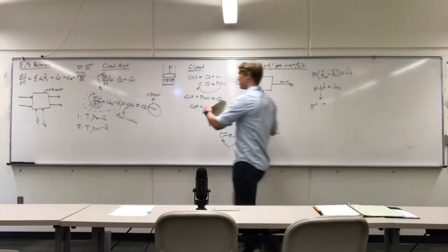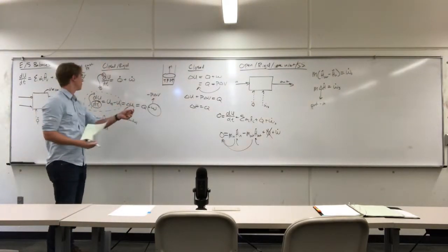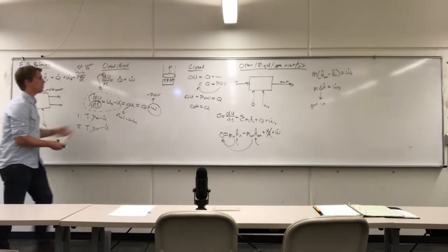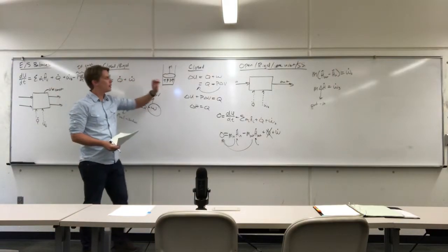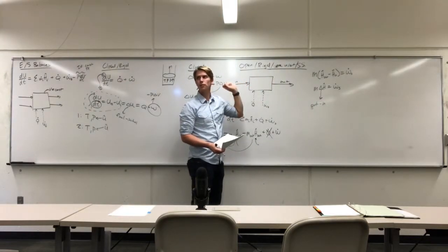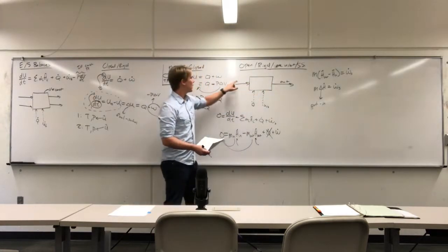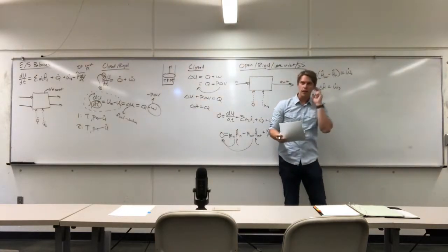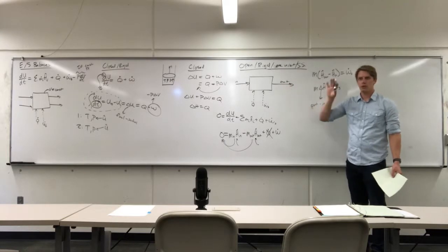You can make a connection by thinking about your reference: the time-dependent one versus the steady state one. In the closed system, there's nothing flowing in and out, so the system makes sense like a piston cylinder device. We basically just draw a line around our fluid and say that's our system. Here, our system is the actual box with streams flowing in and out, so there's mass crossing the boundary. We could also solve this problem by not thinking of it as mass entering or leaving the boundary, but by following a volume element of fluid as it travels through the system and expands. We can think of both of those as appropriate ways to solve this problem. So you can solve most problems as open or closed depending on how you want to do the reference.